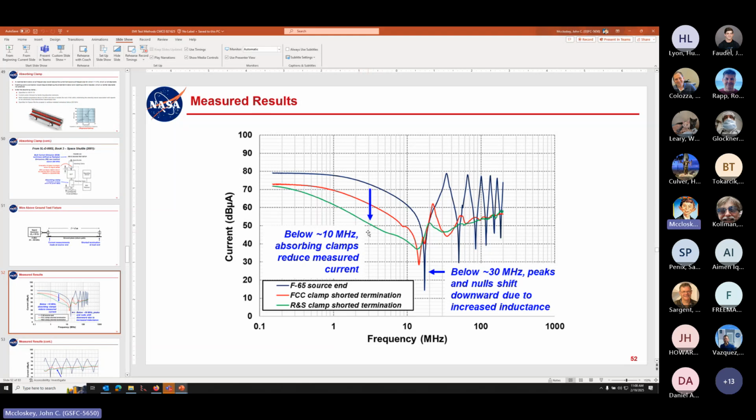John, yeah. I think for the audience, we need to clarify that per CISPR, the absorbing clamp works on an EUT that has a single conductor. CISPR 16 is for drills, microwave ovens. If you have an EUT that has multiple conductors or cables, each of those cables needs an absorbing clamp installed simultaneously. And it's just because it changes the current path when you insert the resistive impedance in series.